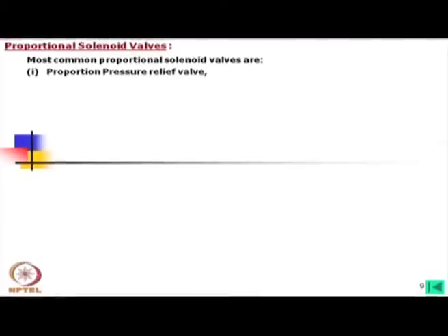Due to that much change, we will get this output proportionally. This means that in setting the relief valve at particular pressures, we can vary that depending on the load we are handling, and by that process we can also save energy, because relieving at a low pressure means less energy loss.